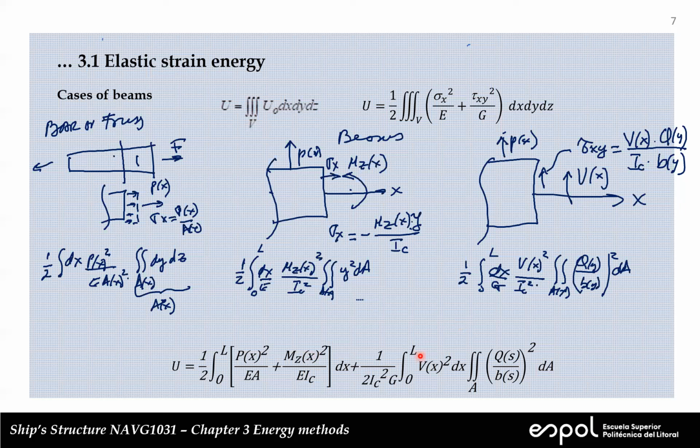Because in statically determinate cases, you can solve for the internal forces: axial force, bending moment, or shear force. And then you can plug it into here and obtain U. And that's what we're going to do in a minute, okay?